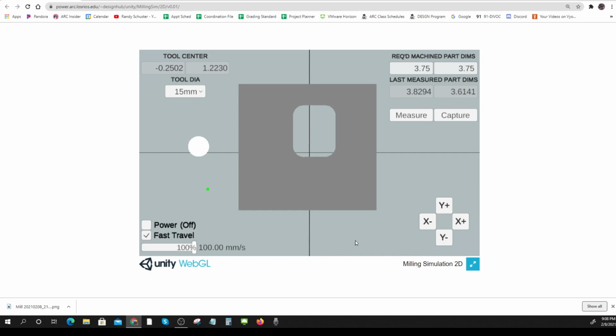So this is for you to practice with. This week, where it says learn the basics of machining, all I want you to do is go to this file, this simulator, make sure that you know what fast travel does, how to set the speed for your fast travel, how to re-zero your 0 point. Just press the Z button. Now my tools are back at 0.